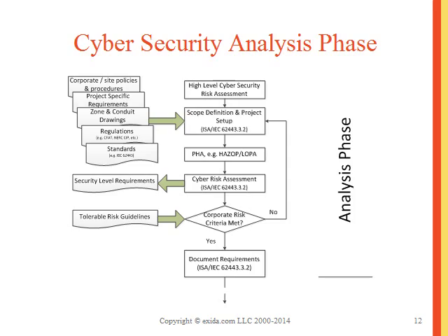So if we take a closer look then at the cybersecurity analysis phase itself, prior to conducting the detailed cybersecurity risk assessment, you need to perform your high-level risk assessment to provide input to that and determine what portion of the hazards that you've identified are specifically security related. So in performing a hazard operational analysis as well as a layer of protection analysis, you go through and identify those components which are specifically cyber related, and then we'll continue the analysis further once those items are identified.